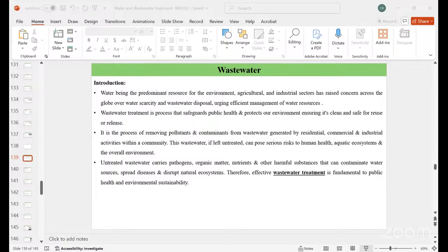And coming to BOD, the biological oxygen demand, it measures the amount of dissolved oxygen consumed by microorganisms during the aerobic decomposition of organic matter in a specified time period, and that is 5 days. The bottles will be filled with water and chemicals, sealed, and kept refrigerated at 20 degrees C and cannot be disturbed. After the fifth day, the BOD levels will be determined by the titration method. High BOD indicates a high level of biodegradable organic pollution, measured by the 5-day BOD test.